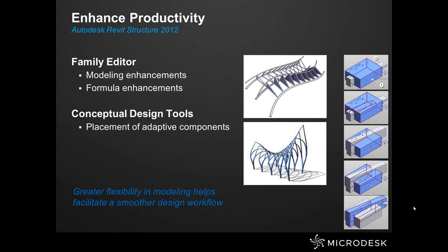Family Editor and conceptual design tools have seen several enhancements to extend their capabilities. Solid cuts and void cuts are now available on family instances of any category in the project environment. You can now perform rounding functions in formulas, and values can be rounded up or down. You can also allow creation of parameters to drive component types in families. Those parameters can be driven by conditional formulas and applied to divided surfaces.